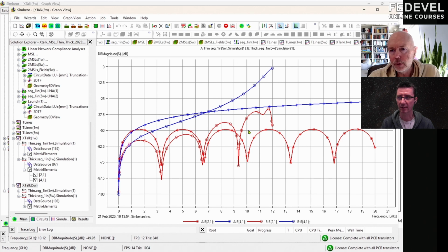So what is kind of acceptable crosstalk for standard signals? What level? Well, it depends. If you take a look at specifications created 15 years ago, like Ethernet specifications for 10G, you'll see very low numbers like minus 70 dB, minus 80 dB, which was really doable.